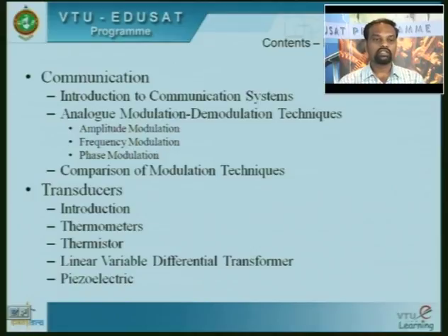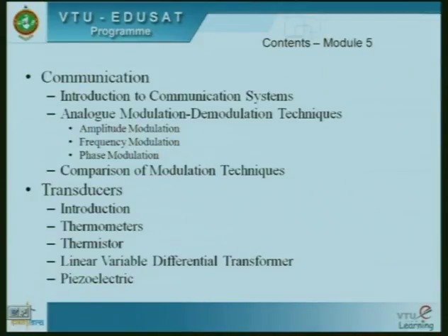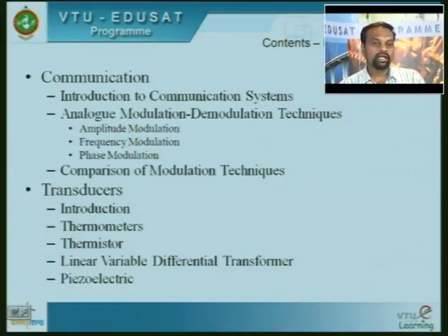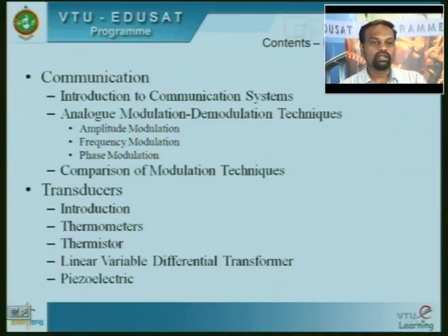The syllabus asks us to go through transducers such as thermistors, thermometers, linear variable differential transformers, and piezoelectric transducers. We will try to understand the working principle behind these transducers, and the applications where they are going to be used.